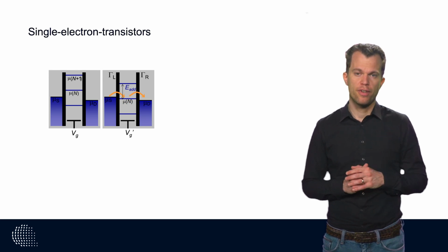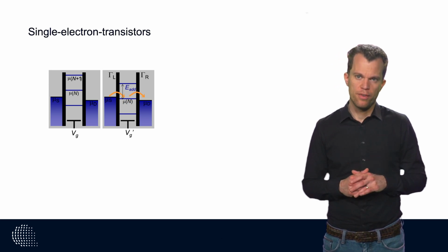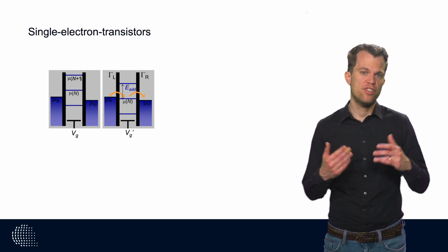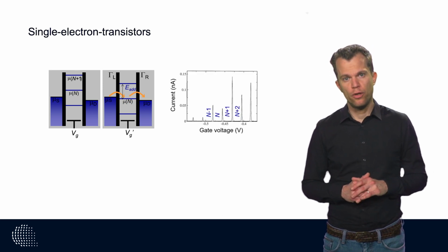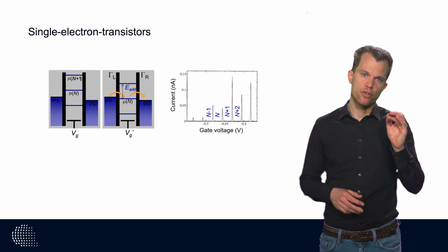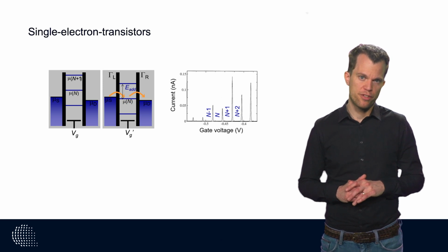And as a result, upon changing the quantum dot gate voltage, current can flow depending on the alignment of these energy levels. When operating at very low temperatures, at or below 1 or a few Kelvin, current peaks at very sharp positions in voltage space.